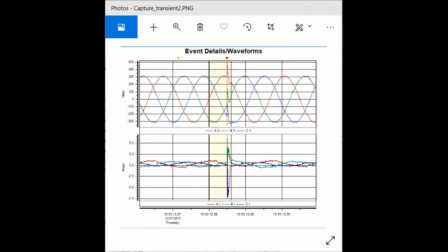And obviously if you have the power monitoring instrumentation that's capable of recording this, the ideal thing that you look for is what we call a consistent correlation, where you have a recorded event and something happened within user equipment, either something failed or it locked up. And because our instrumentation records the time and date, you can draw that correlation. So if you have that consistent correlation, then you know that is causing a problem. Then the next step obviously is to mitigate it.